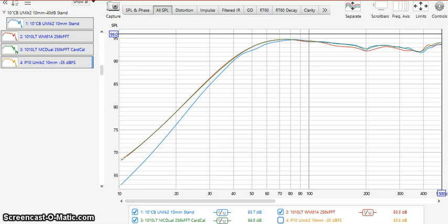So if you take a look at the graph on the screen here, I've got 4 measurements loaded, 3 of them shown. You'll notice the upper one, that's sort of reddish black, there's nearly perfect overlay between the Panasonic microphone through that separate preamplifier and the mode compensator dual system, at least from close to 100 hertz down, and it's within a dB up to the limits of 500 hertz of the graph that's shown.